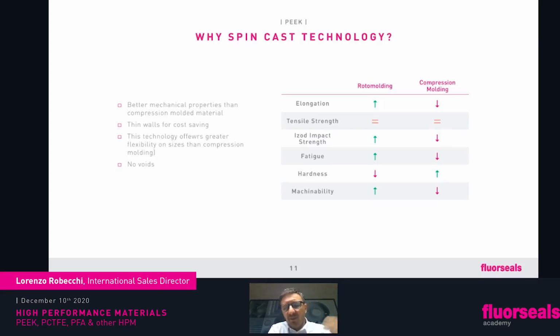You can do an extra annealing. We do extra annealing. This is going to help up to a point. And the problem is that no matter what you think of, you never really know what's going to happen when you machine it. Because you can't say, oh well, it's going to shrink 0.5%, it's going to shrink 1%, it's going to shrink 1 millimeter. You never know. In my experience, it's very hard to tell. Too many things come along. It depends on how the billet has been processed, on the powder, on the wall thickness, on diameters. You just have to live with it.